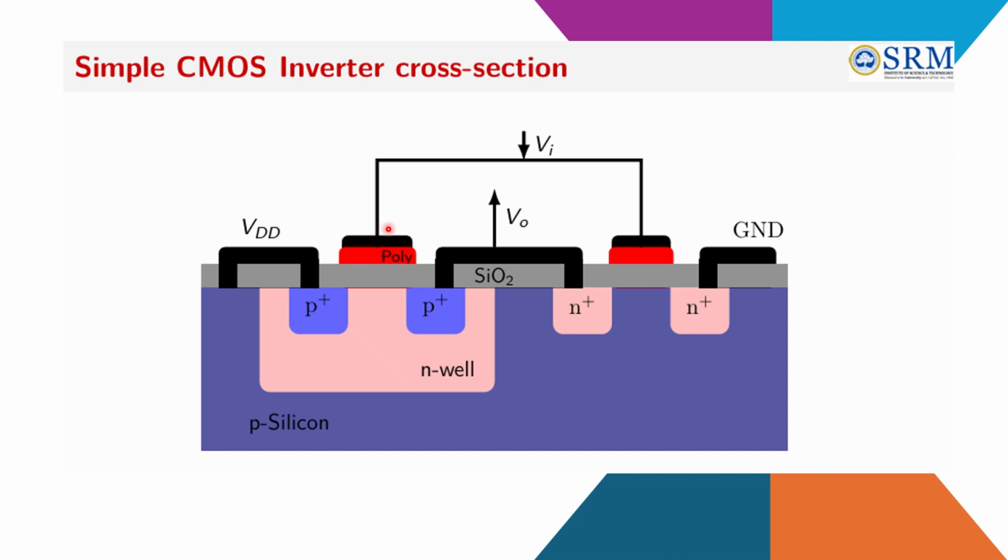And then the black color is the metal contact, that is how you develop the contacts, right? Ion implantation can be used to develop the diffusion regions, and you can use diffusion to develop the drain. Then the oxidation process, then deposition technique, then metallization technique, and the etching. All these things you can use. Then annealing at the end. So this is the summary, right?